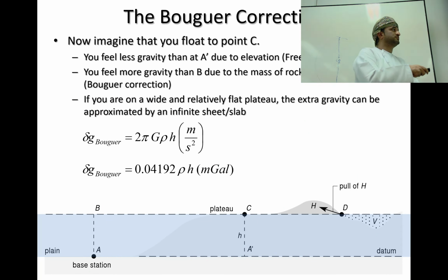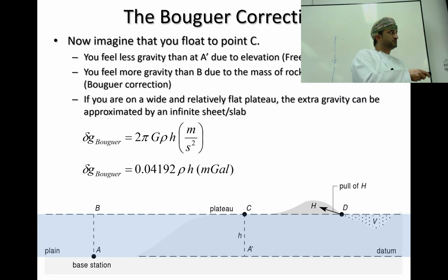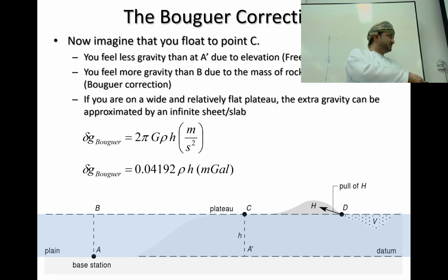So what's the unit we use? Milligal, per meter. Milligal per meter, every meter you move up and down. One might ask, okay, we know H. H is basically the elevation from the base station. What about density? Where do we get it from? Yeah, the density from crust.